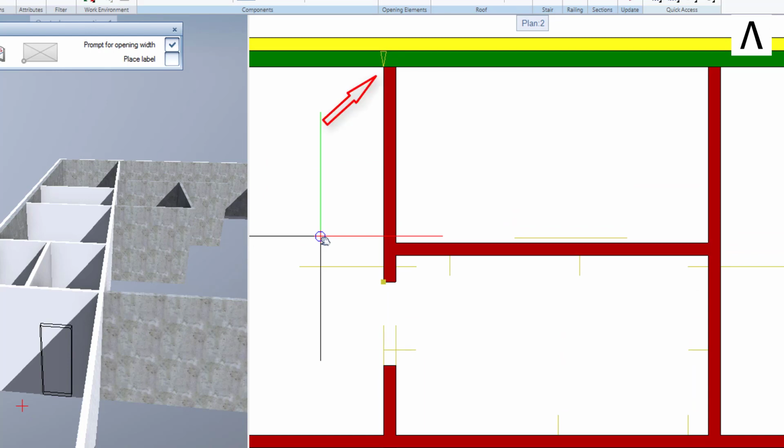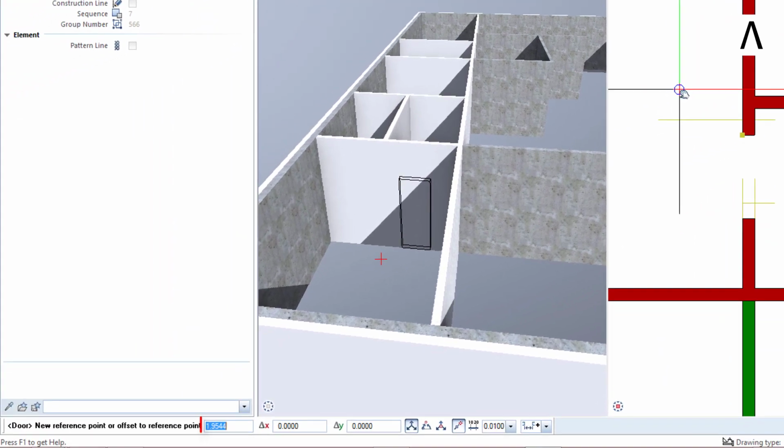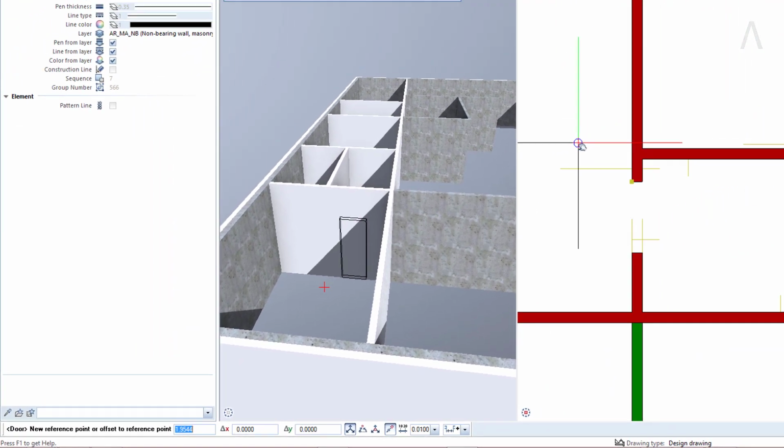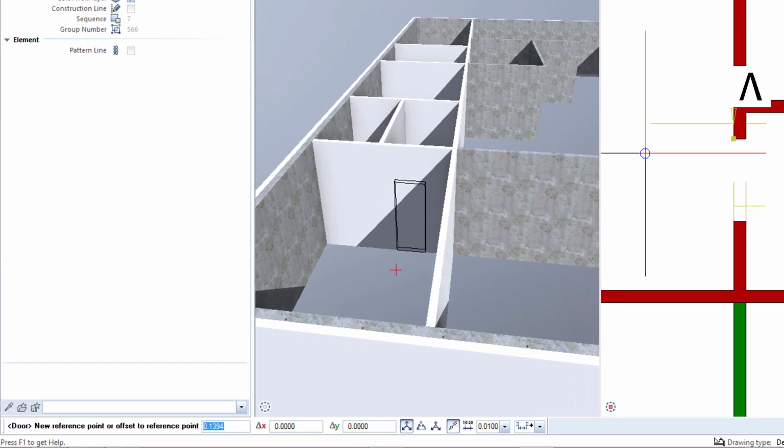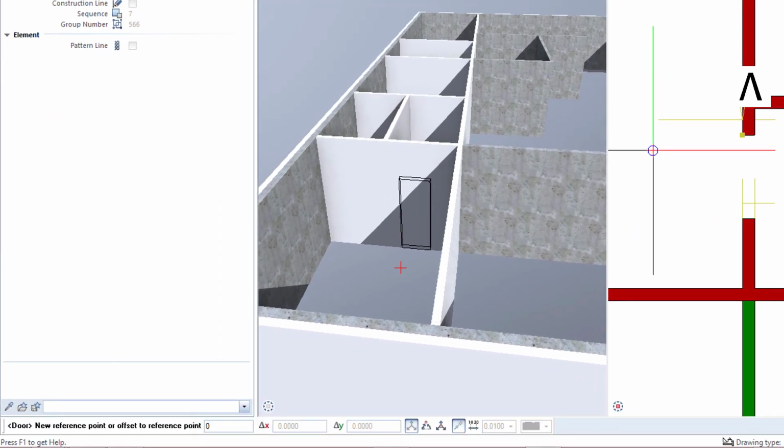The offset between this and the small square is specified in meters below in the dialog line and should help me with the entry. I could now change the value here and confirm it by pressing the Enter key if I had considered a value for the doorstop. However, since my doors are to be placed at the points marked at the extension lines, I simply left-click on one of the points. Allplan places the arrow there, and I change the entry in the dialog line to 0 because my door is to begin exactly at the arrow with an offset of 0.